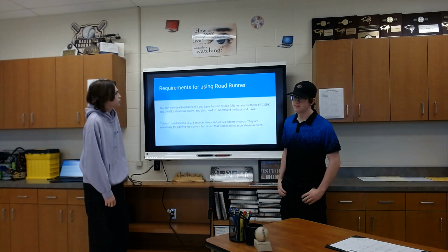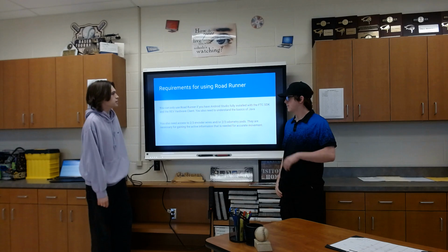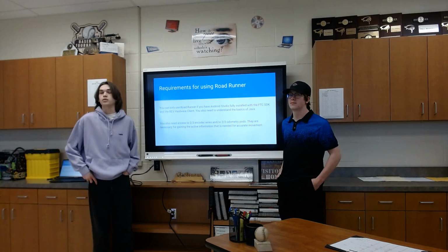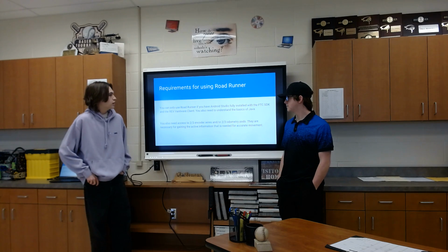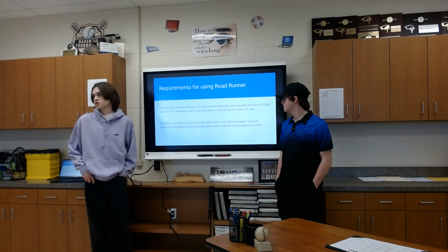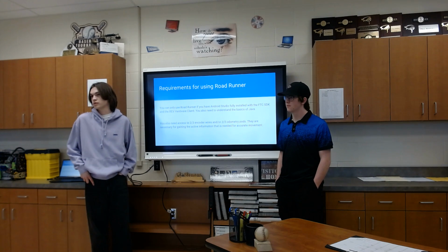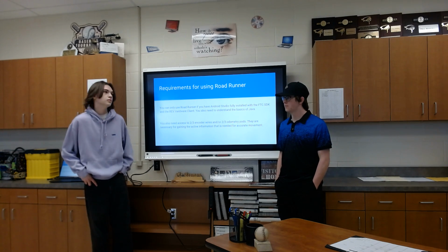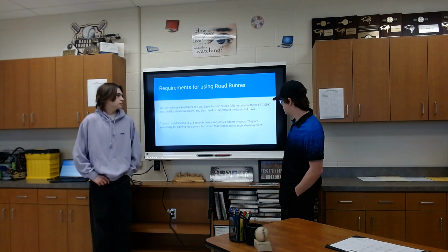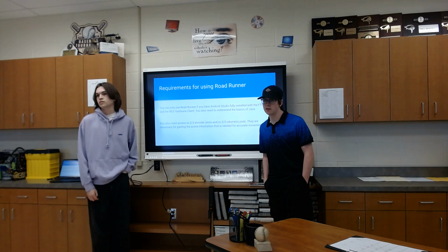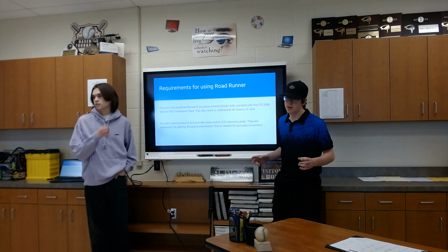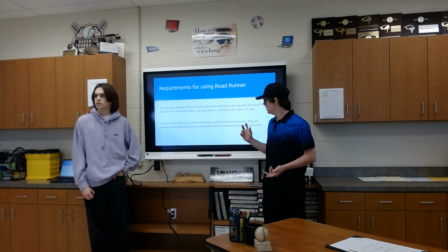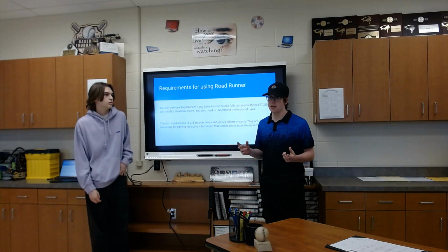So, Roadrunner requires utilizing Android Studio and having it fully installed with the FTC SDK and the REV Hardware Client. We also recommend having a basic understanding of Java, that way you are not throwing yourself into a very complicated programming application. You also need to utilize motor encoders or odometry pods so you can track your robot's movement on the field and overall just make your autonomous more accurate.